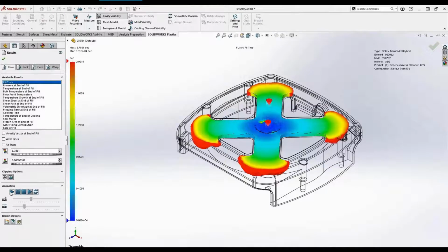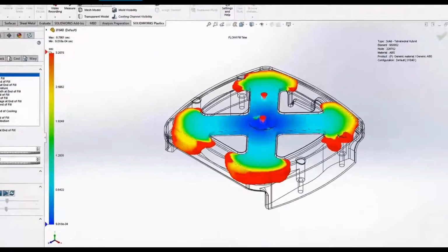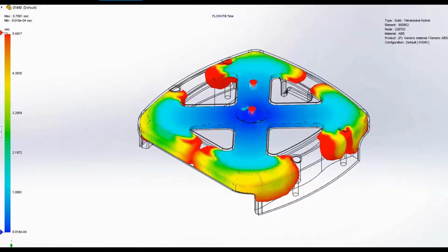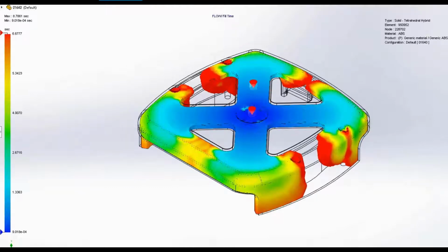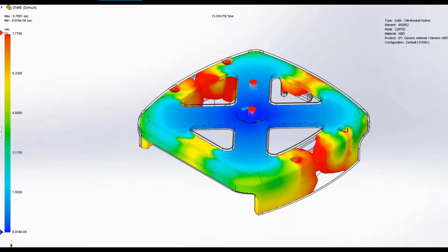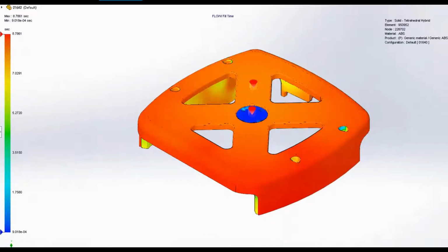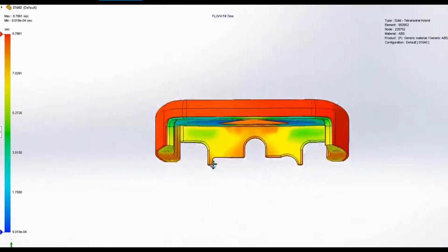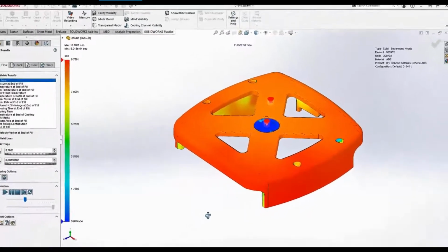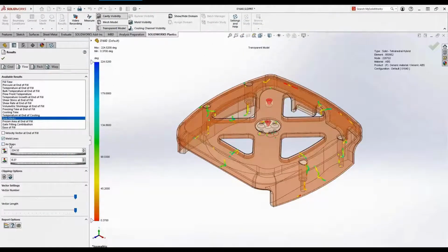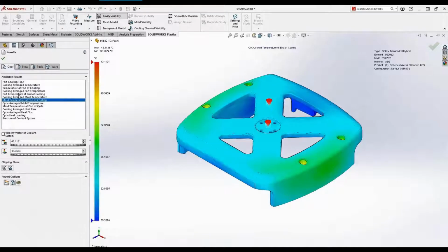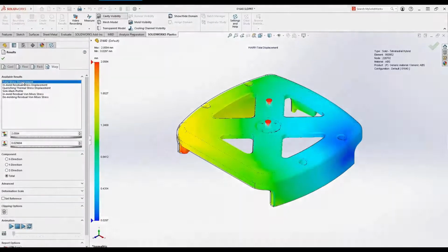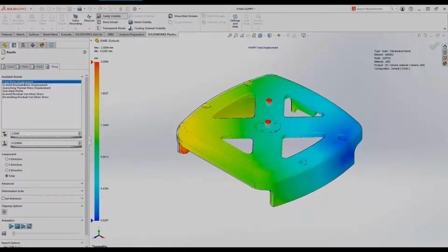They are now fully meshed and modeled appropriately, giving you more accurate simulation cooling results without the need to fully model the cooling channels and the physical components that make up the special inserts like you have had to do in the past. By defining the entire simulation study on the 3D model and virtual domains, it has enabled a more dynamic workflow where you can look at and evaluate different scenarios in your design before any of the heavy lifting is done. The results themselves, which include the new multi-material overmold injection process, are now more accurate when considering cooling, giving you confidence in your injection molding process before you even start designing or investing time and money into the mold itself.